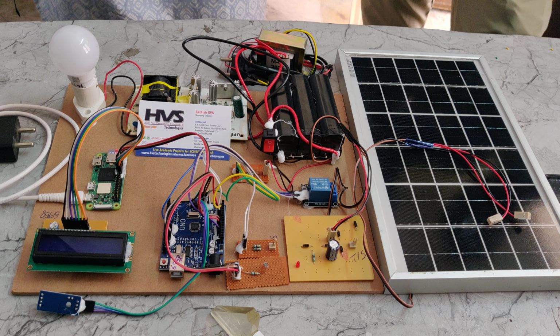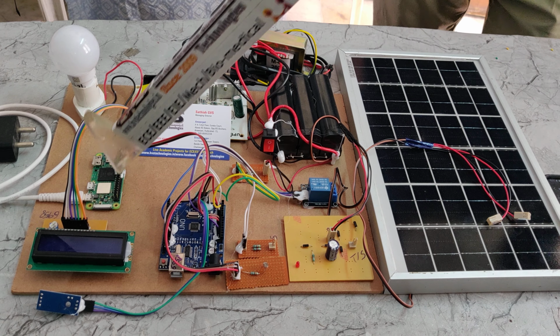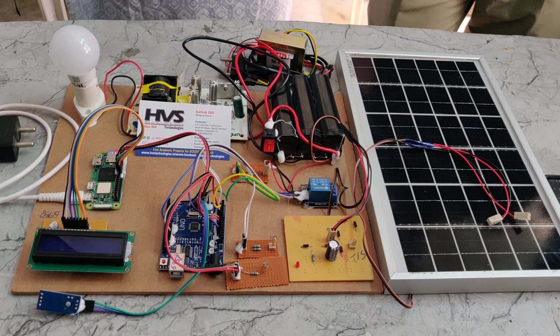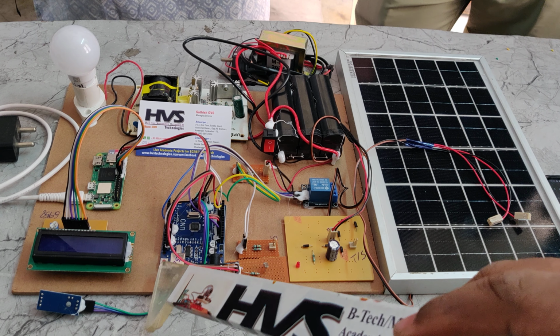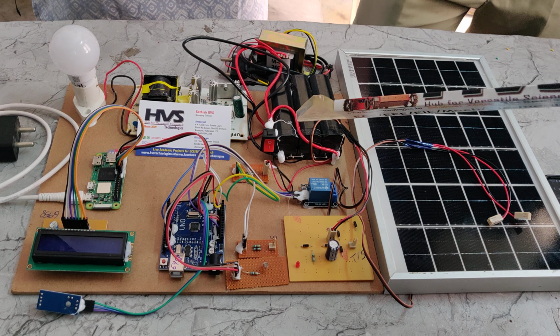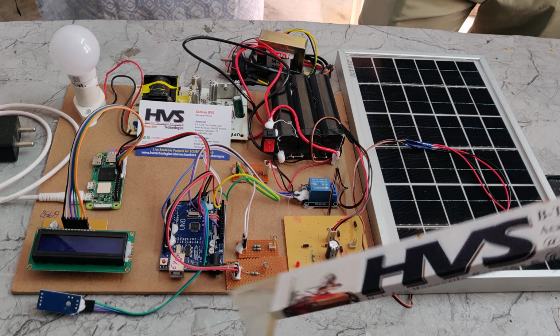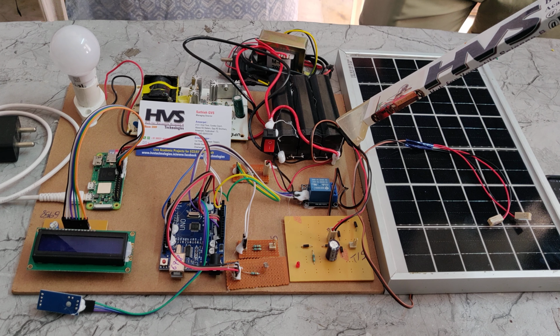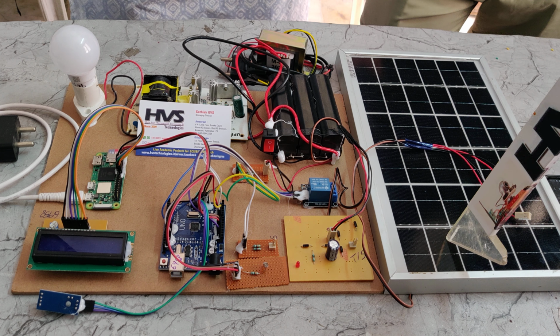The main processing unit in our project is the Raspberry Pi. This Raspberry Pi will take care of the input of these sensor data, which will be converted from analog to serial with the help of this Arduino Uno board. We are also going to continuously measure the battery voltage with the sensors, and the same voltage will be monitored by the Raspberry Pi, and it will control the relay whenever the battery voltage is low. So the main purpose is continuously monitoring the solar panel status with the sensors.